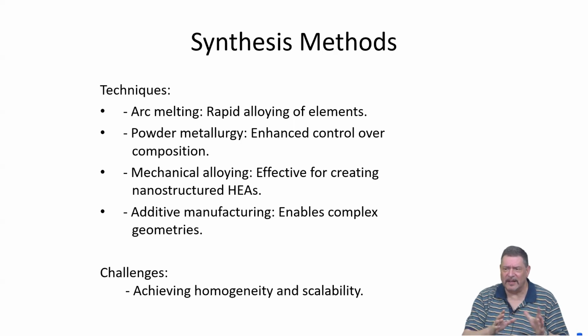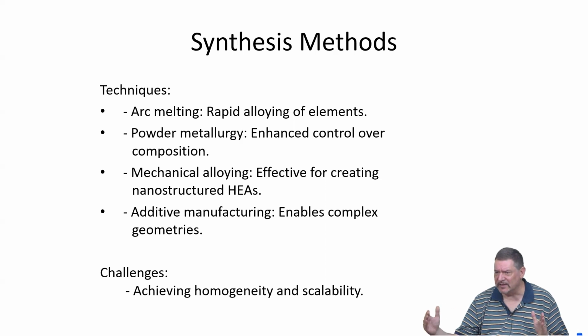But the nice thing about the high entropy systems is, as I told you yesterday, they can store a lot of defects because the dislocations cannot glide very easily because of these lattice distortions. And that means that you can still retain small grain sizes while making the material compact. And this has been shown to be working and to be efficient.